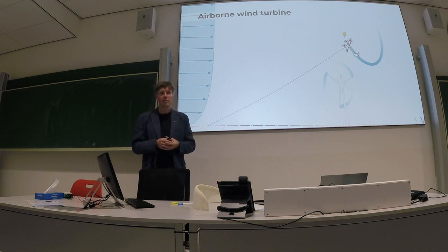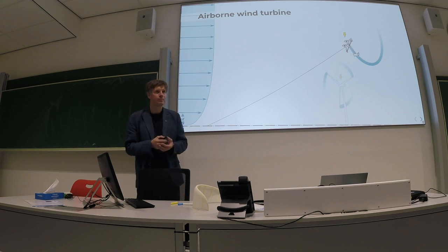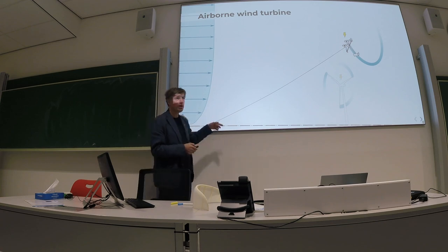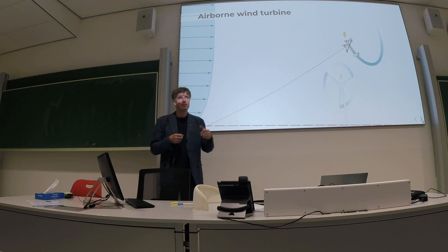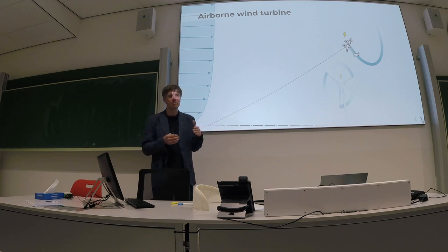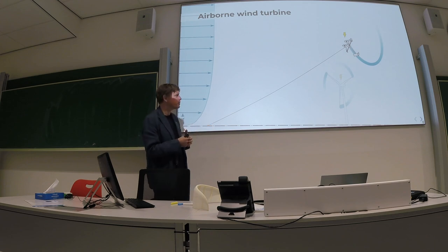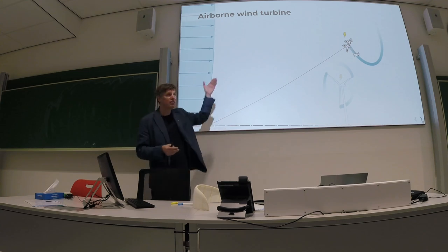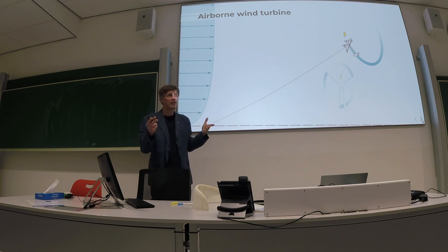I mean more in terms of how large is the percentage? Oh, the percentage. When the tether is short, the percentage is very small. Let's say if you have a tether of 100 to 200 meters, you probably have 10% drag contribution from the tether. It depends also on the size of this installation. For large kites, I think the tether drag decreases relative to all drag.